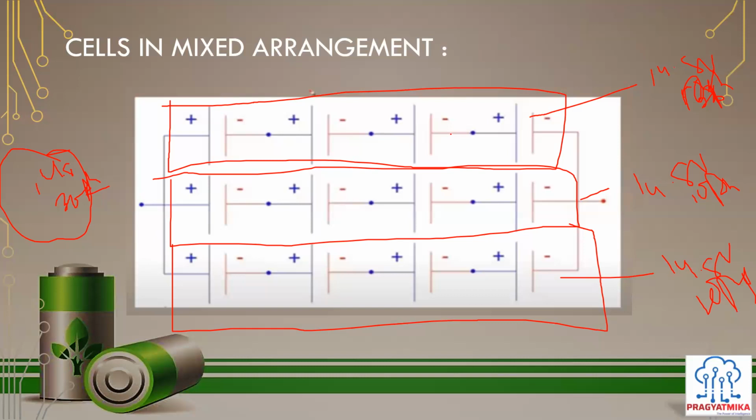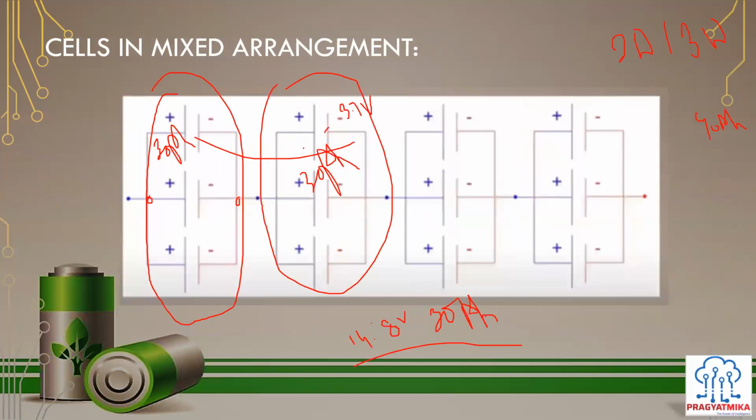Apart from that, these modules have to eventually be joined together. If we connect the cells in series as one module, and then connect the modules in parallel, that would be easier to join in my opinion, because all the positive terminals from all the modules you can connect together, and all the negative terminals as well. But in the other case, you would have to figure out an arrangement so that the negative and positive of modules are together, because welding might become a problem when joining those cells. Welding is easier in this one if you do it physically.